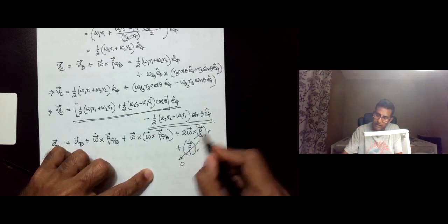And we right away note that this is 0 and this is also 0, and that is because the points C and B are located on the same rigid body, and the rotating reference frame that is considered is a reference frame that is fixed on the rigid body itself. That is, omega is the net angular velocity of the rigid body itself. So omega is omega d3.